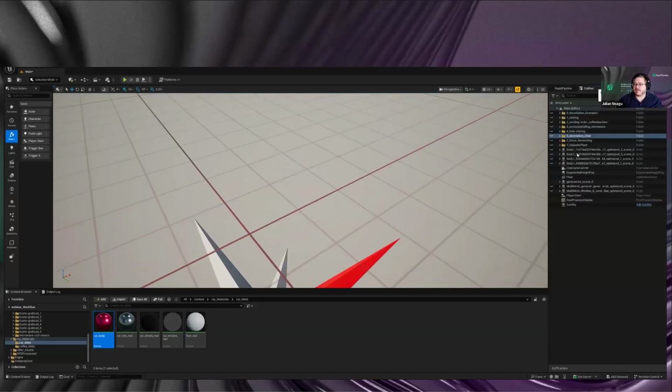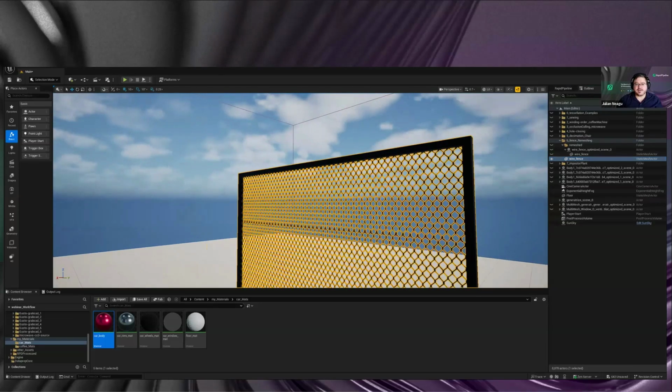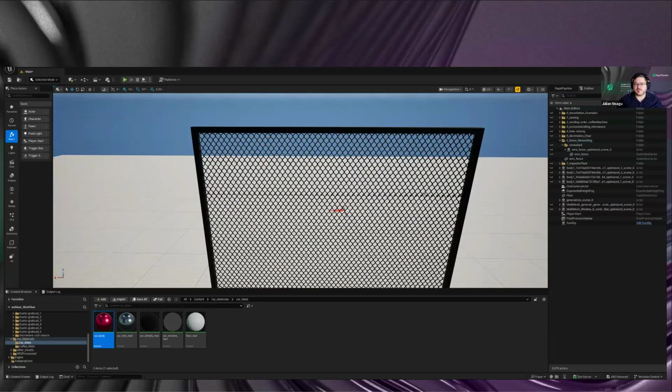Yeah, let me quickly show the remeshing option we have. And in this demo specifically, we are actually looking at alpha baking as well. So usually when we perform remeshing, and that's maybe one of the main differences to Unreal, is that we don't by default preserve the original texture coordinates and UVs, because with a more aggressive remeshing, shrink wrapping, the UV coordinates will shift, and you will have issues with the accuracy in terms of the texture projection.